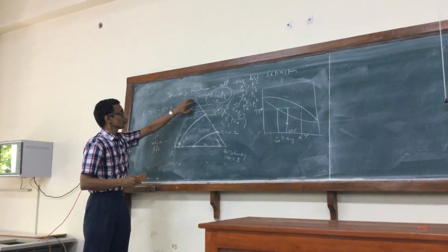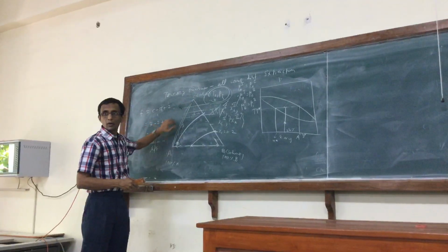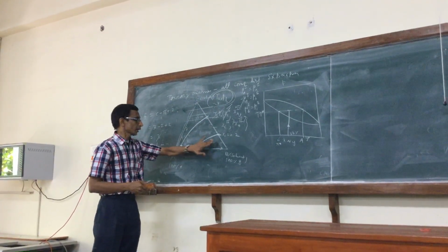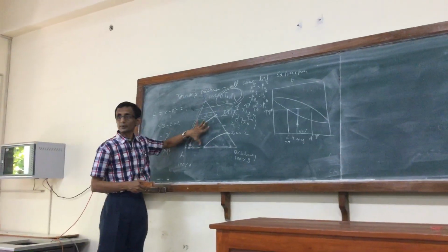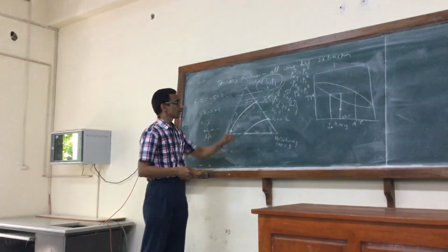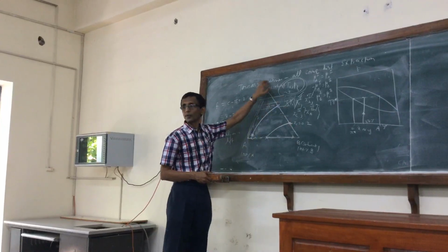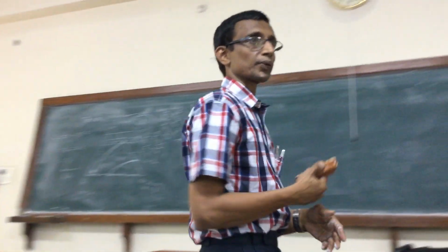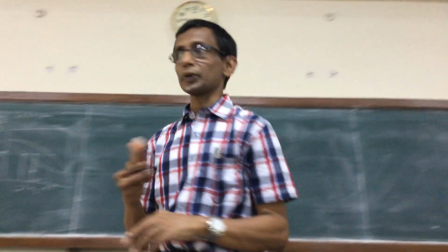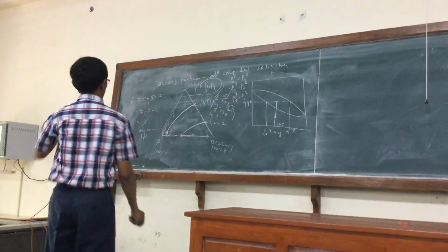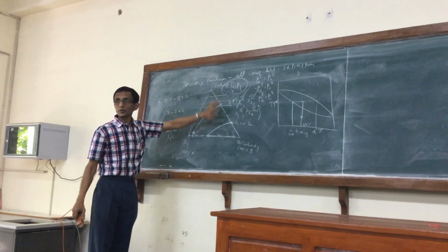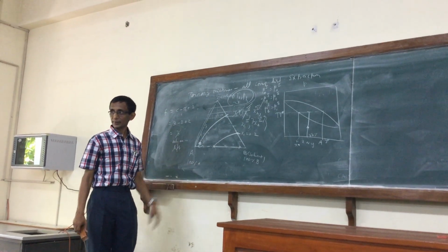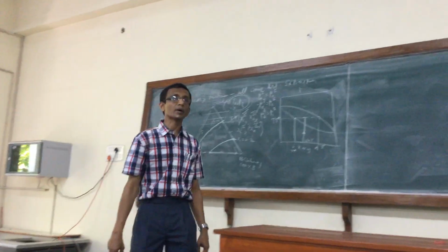So here you can see that AC is homogeneous in all proportions, but not only AB, but again anything within this envelope is 2 phase. Everything else is single phase, right? And so we can see BC also can split into 2 phases after a certain composition. So you have to know how to interpret this. But those are all 2 components. You can also get a 2-component phase diagram in that, right? From this diagram. Are there any questions?